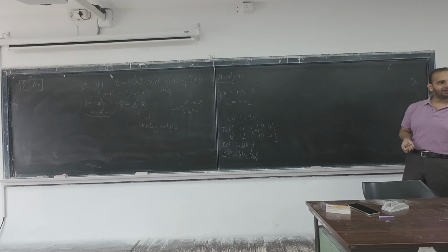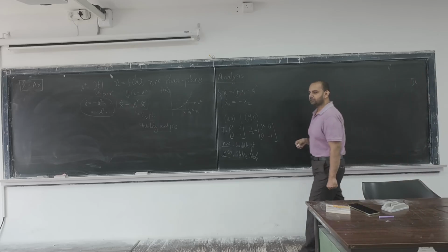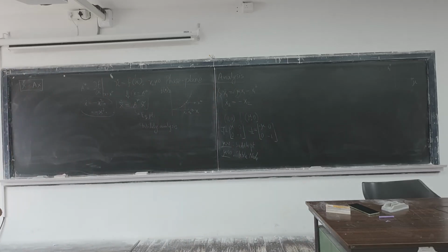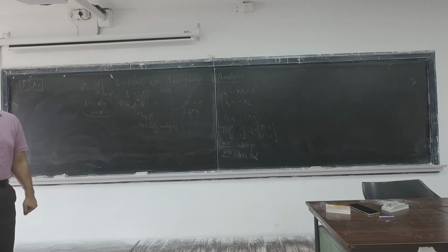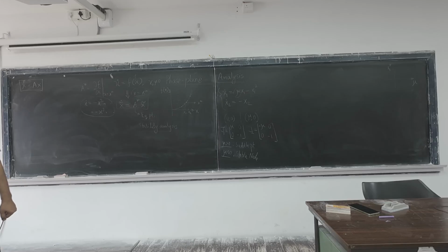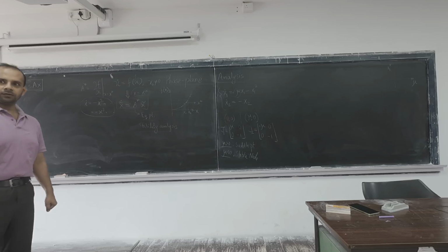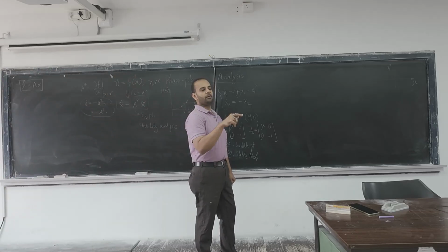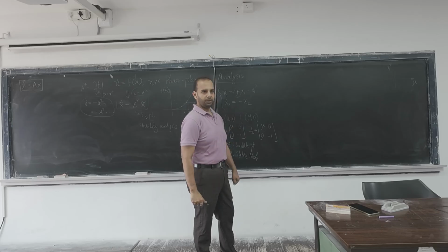To give you that example, I took the undamped Duffing equation, right? In the case of the undamped Duffing equation, for the positive range of mu we had only one equilibrium point, or maybe for the negative range of mu, I am not exactly remembering. For the positive range, we had only 0, 0, right? But if mu is negative, then we got 3 equilibrium points: one is 0, 0 and the others are plus minus root of mu, comma 0, right? So for the negative range of mu there are 3 equilibrium points. However, for positive mu, there is only one equilibrium point.